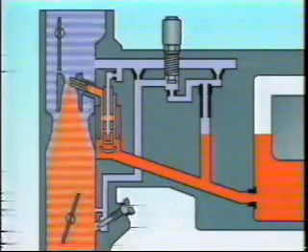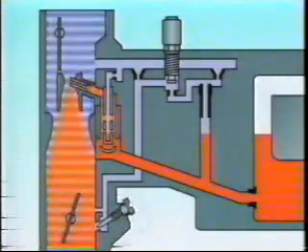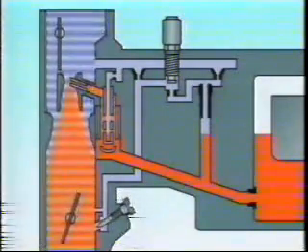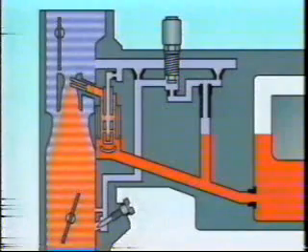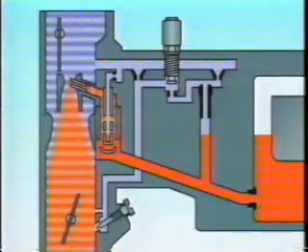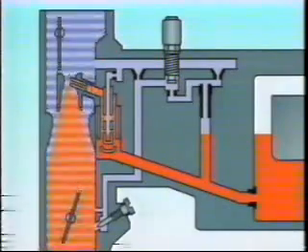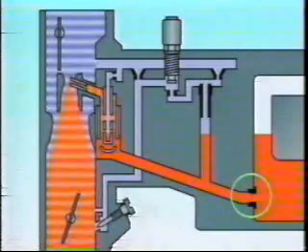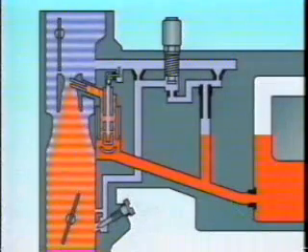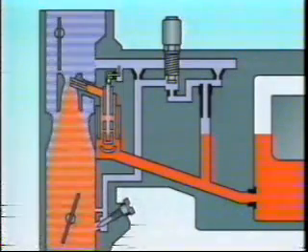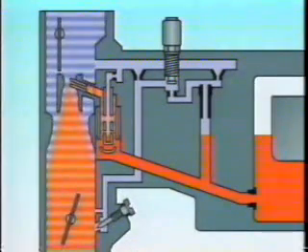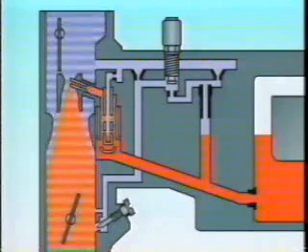The primary high-speed circuit works as follows. When the throttle valve is opened wide, allowing for a higher speed and volume of air to the Venturi, the amount of fuel that is delivered is equivalent to the intake air volume drawn into the barrel. The amount of fuel is controlled at the main jet before it is mixed with the primary air bleeder and injected from the main nozzle.